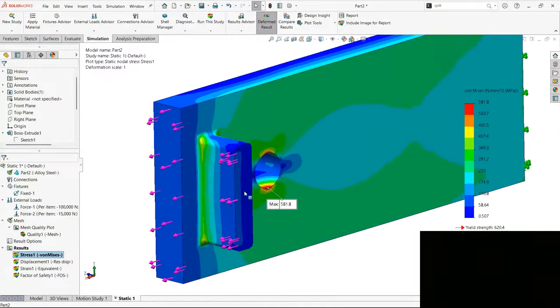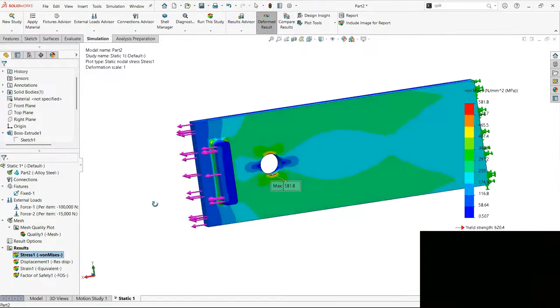In short, if you want to reduce this stress hotspot, what is the best possible solution? I would recommend having a fillet here, right? But again, there might be some disadvantages with respect to the machining. The manufacturing cost might increase, but you can propose a solution to the counterparts. If they are okay with that, they will proceed, or else they will tell you to remove the complete hole, if not necessary. Or else you can even do the topology optimization on this one.